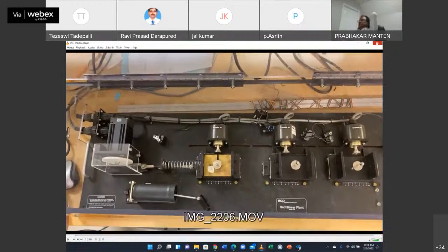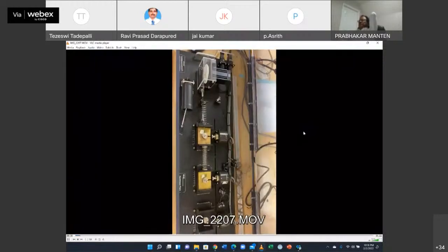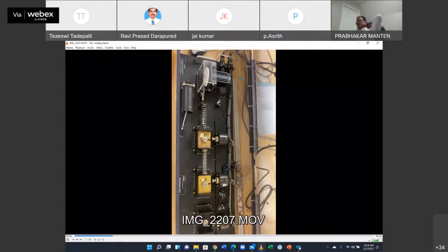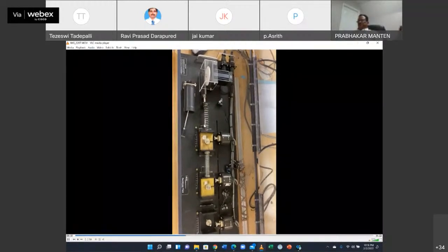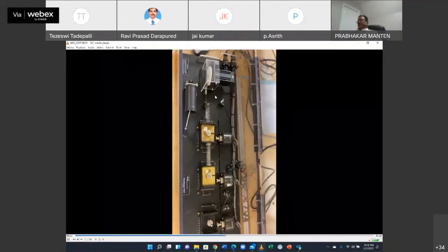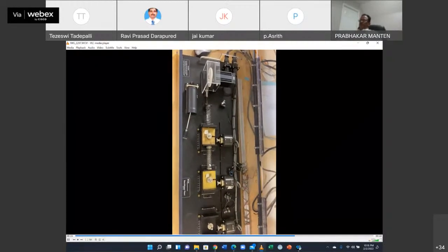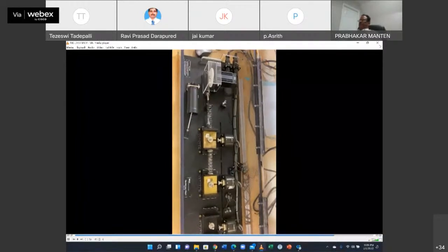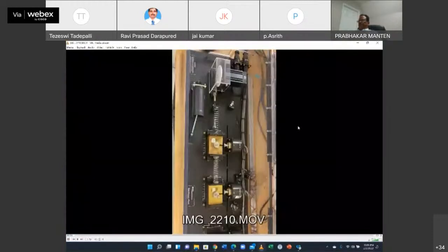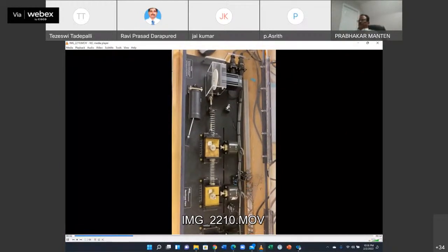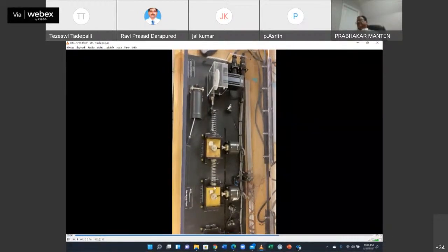So let me show you the 2 degree. I think we captured up to 2. I didn't have the third one with me here. If you do the same thing in the 2 degree of freedom system, you see 2 masses connected. This is the first mode. They calculate theoretically using mathematical formulations and excite at that frequency. Then they see both lumped masses going in unison, right? Now the second degree, the second forcing frequency, should be marked somewhere on the picture. When they move to that, these two go in opposite directions. See that? At that frequency.